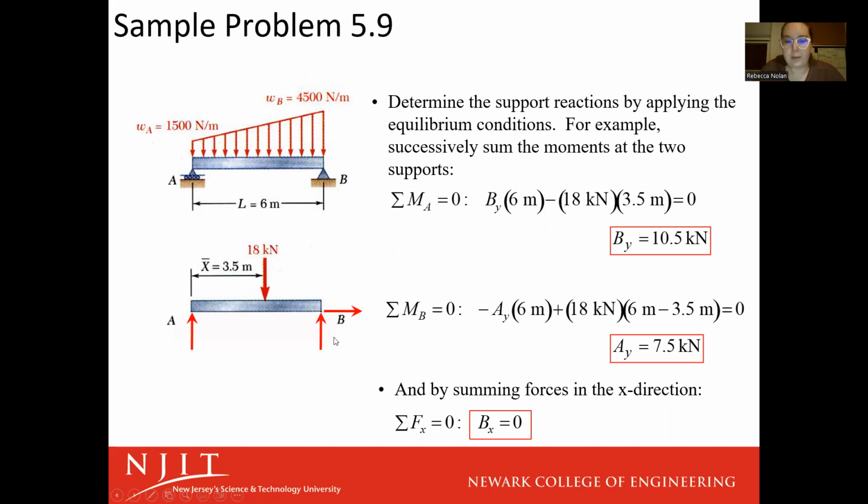So B, the forces at B, we're going to call this By and this Bx. By and Bx both go through that point, meaning that the perpendicular distance is 0, meaning that it has no impact on the moment. Right now, our unknown values are Ay, By, and Bx. So we're getting rid of 2 unknown values and we still have 1 unknown value that we're left solving for.